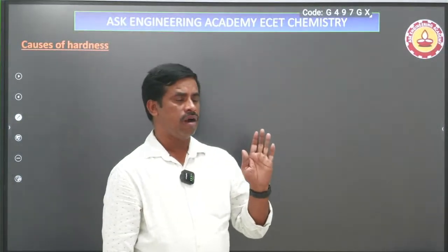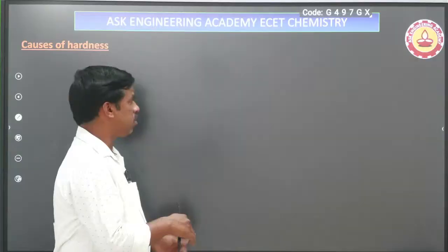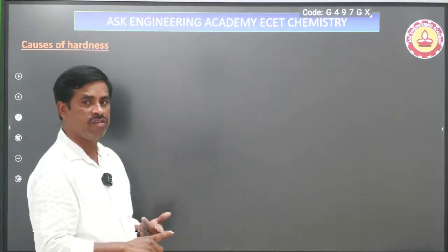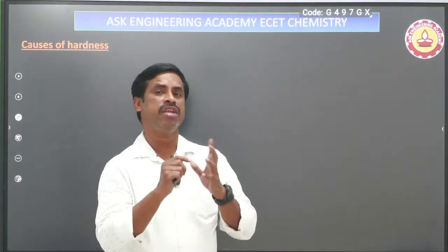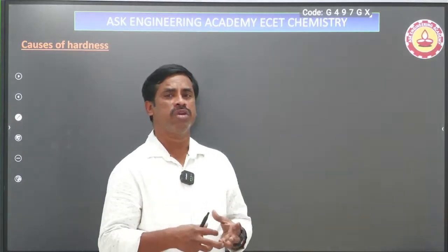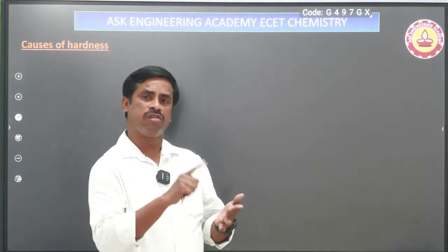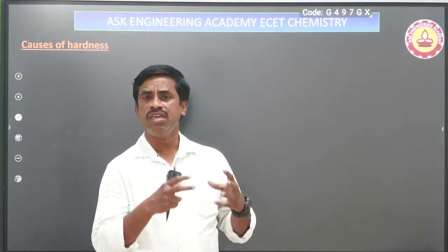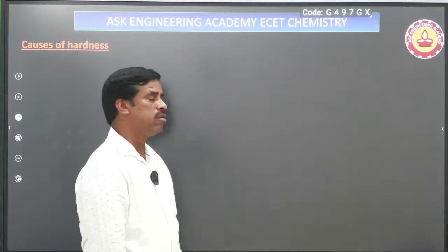Next, causes of hardness. What are the salts causing hardness? Different calcium and magnesium salts are causing hardness. I am writing here: bicarbonates of calcium and magnesium, chlorides of calcium and magnesium, sulfates of calcium and magnesium, and nitrates of calcium and magnesium, etc. Whatever the source, either groundwater or surface water, these salts dissolve in that water, and absolutely they do not produce much lather.